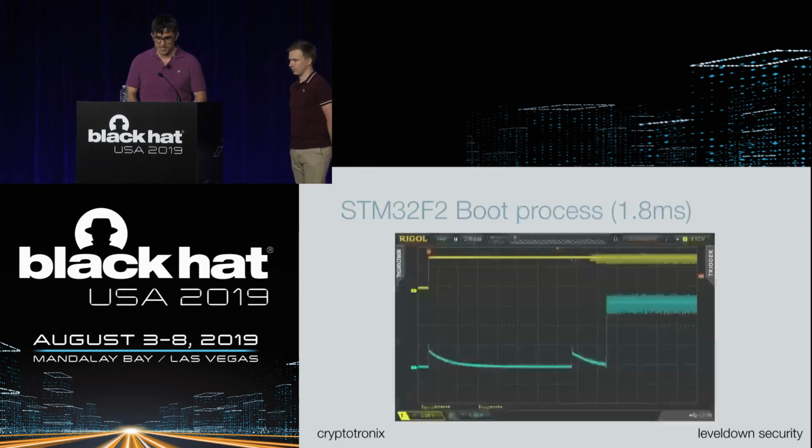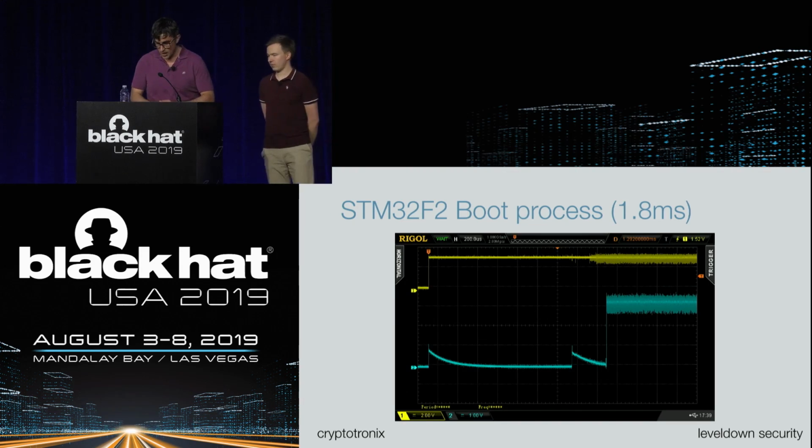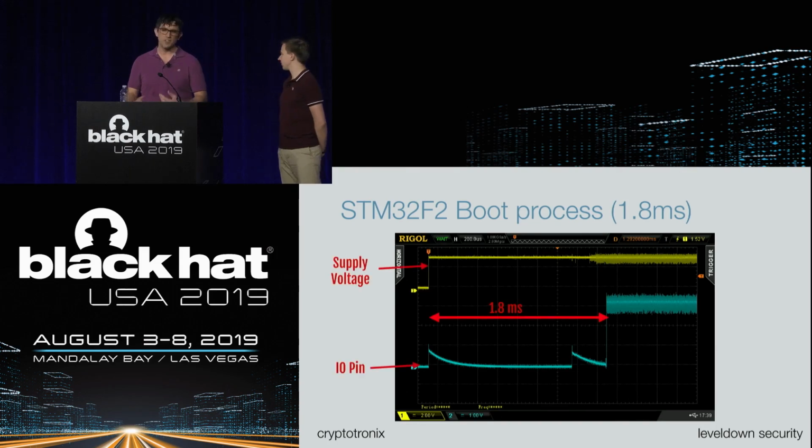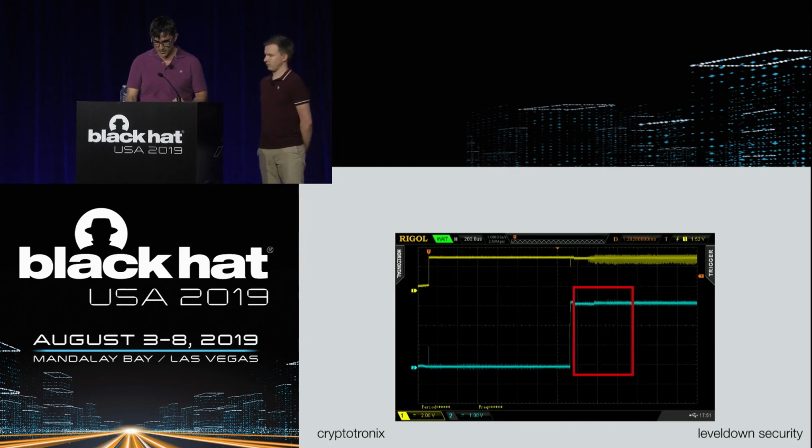So we're still in that investigative phase, still trying to learn about the target. What we now recommend is, before you move on to a new target, you study the boot process with an oscilloscope and figure out some timing information, because that's going to help you figure out your delay and where to apply the glitch. Here we're looking at the oscilloscope of the supply voltage on the top and an I/O pin on the bottom, and we're just trying to measure the time to user code, which is about 1.8 milliseconds. That's how long it takes to get booted into user code. And we can tell that because there's lots of interesting activity.